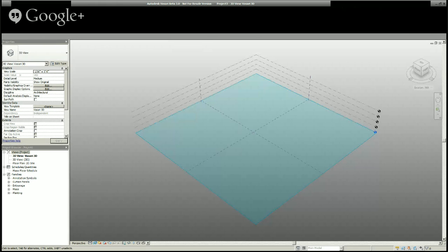Now, at the top of Dynamo, you also see a series of menu drop-downs. The most important one that we'll look at today is View, because that's going to allow us to turn the background 3D preview on and off in our workspace. It'll also allow us to change the connector types if we want to look at the different types of connectors that Dynamo allows you to use.